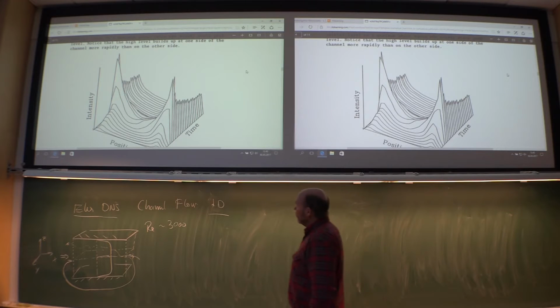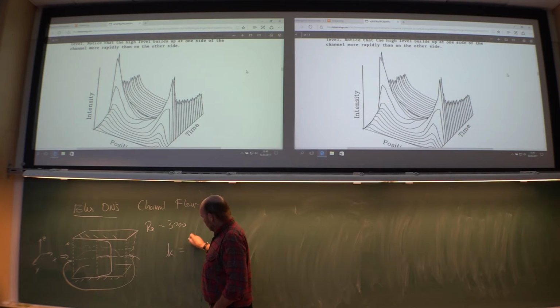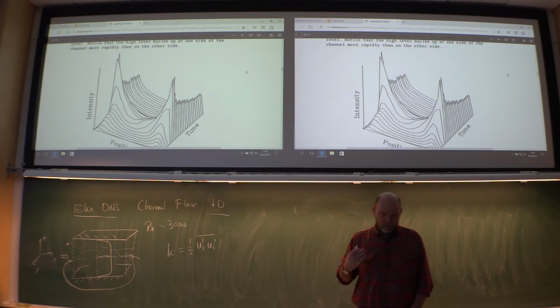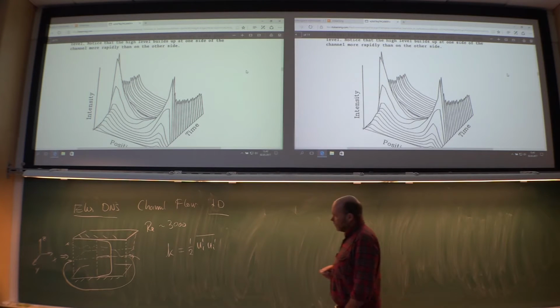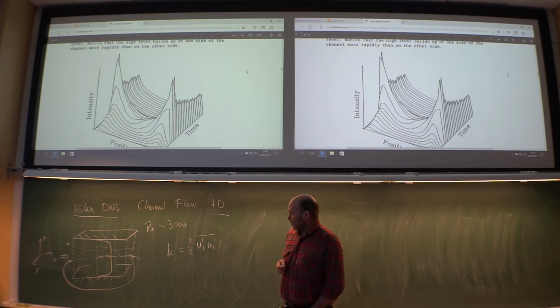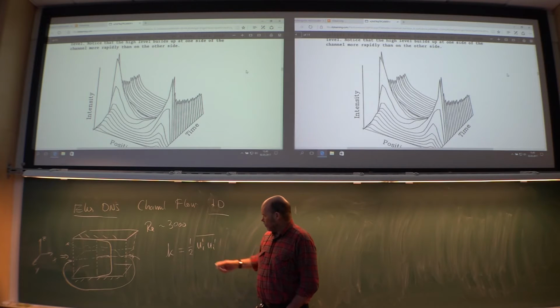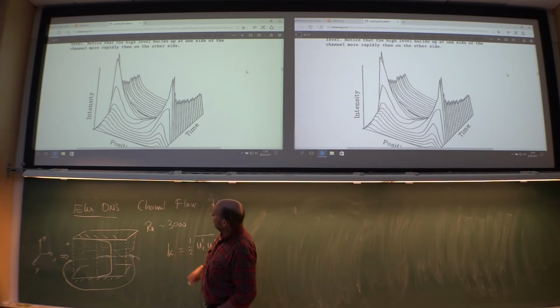So what I did was to have a look at the turbulent kinetic energy, which is u_i fluctuation averaged, sort of the sum of all these intensities: u' squared plus v' squared plus w' squared. And then you can create sort of a turbulent kinetic intensity or energy, if you like. This now being one single point. What I can do here is taking a total average.